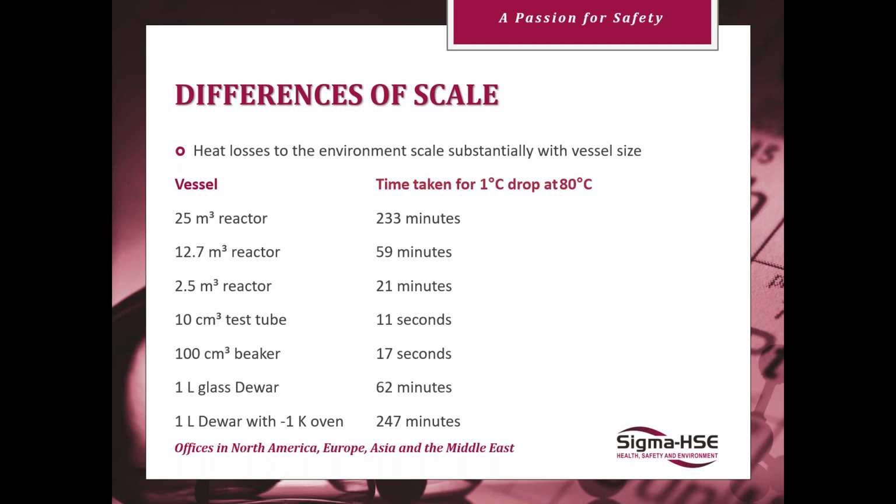As the reactor size decreases from 25 cubes down to 2.5, the time the vessel takes to drop 1 degree, starting from 80 degrees, goes from 230 minutes at 25 cubes to just 21 minutes at 2.5 cubes. So that's an order of 10 for both the reactor size and the time it takes.